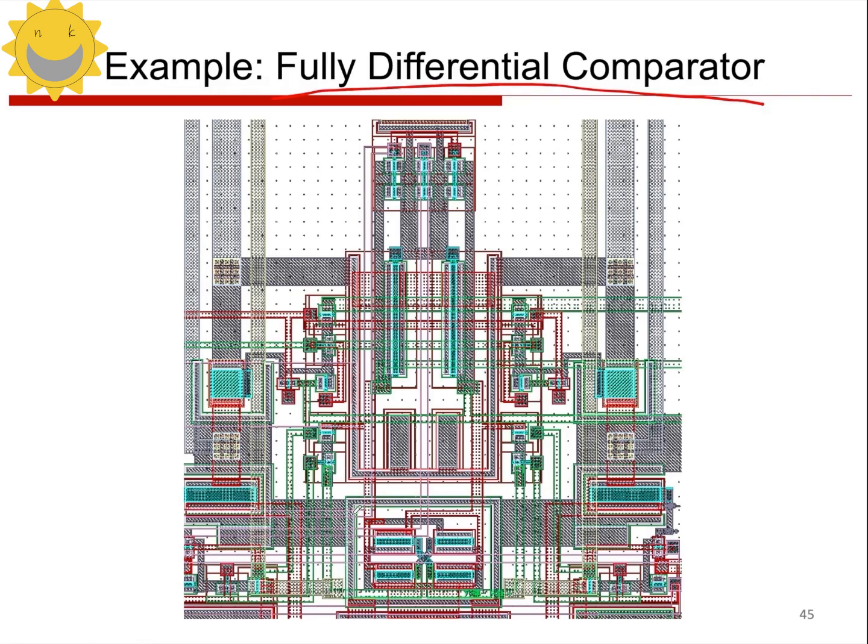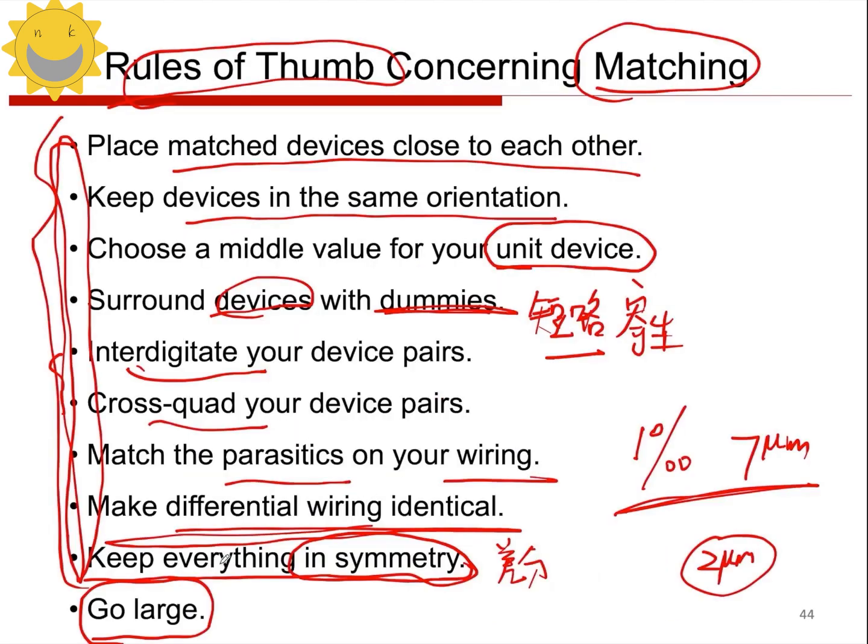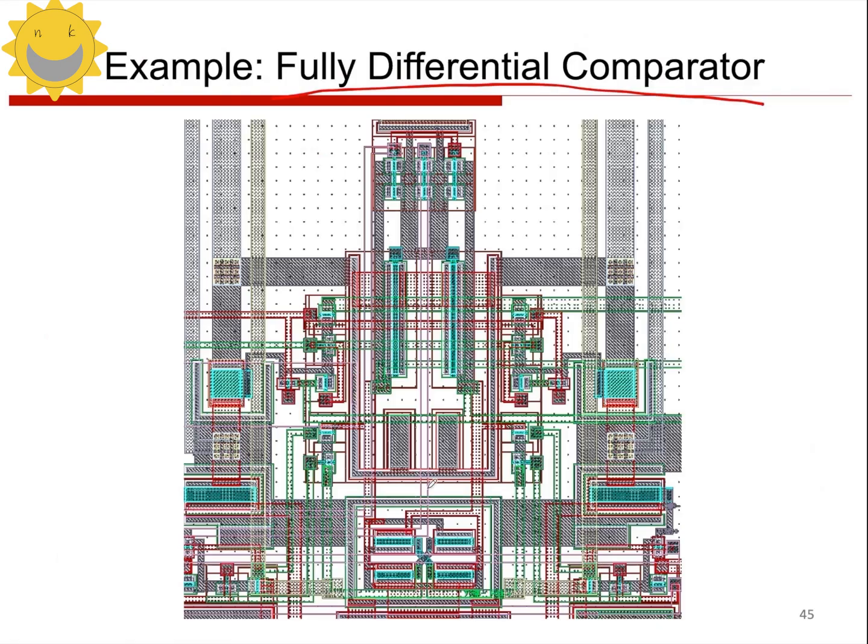This layout has a central axis. For example, there is a central axis here. It folds along that axis. After folding, they overlap. This gives a symmetrical structure, meaning both sides are identical. This benefits our circuit by suppressing common mode noise. With this as the central axis, I can fold this layout in half.